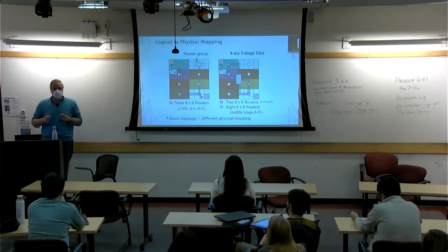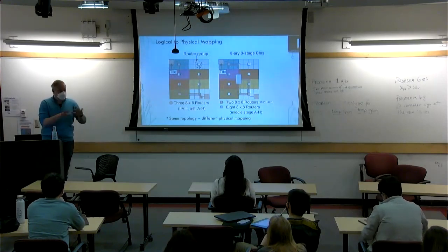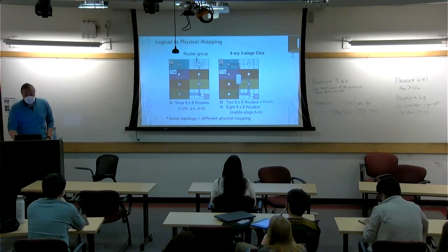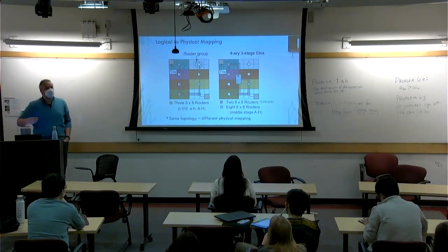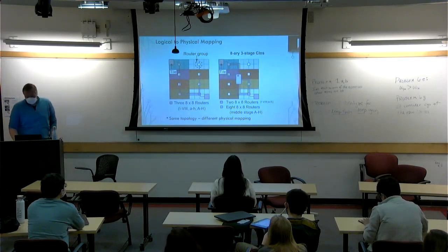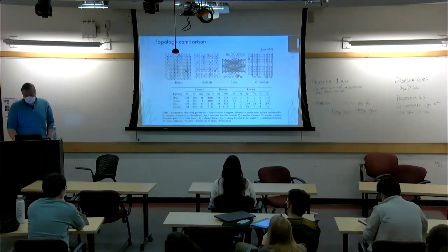I can't have one switch to switch traversal last 2 cycles and another one last 1 cycle. Everything has to be kind of uniform. So that's bad. Now, if you put everything in the center, all the middle switches in the center, then you cut basically almost by more than 2x the longest wire route. Right? So you can save some power, save on the latency as well. Okay.